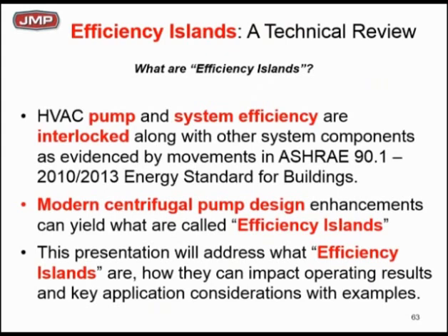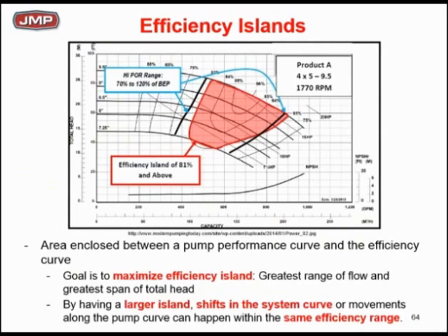We need to look at that island a little bit, and we got to define an island. So here's an island for you, and I'll flip through several of these slides pretty quick. I think you already got the concept. We need to look more than just BEP. There needs to be an envelope or some definition of an efficiency island, and we need to match it up to the real world of constant head, making sure the pump head loss calculations are correct to get the true operating cost of our pump.